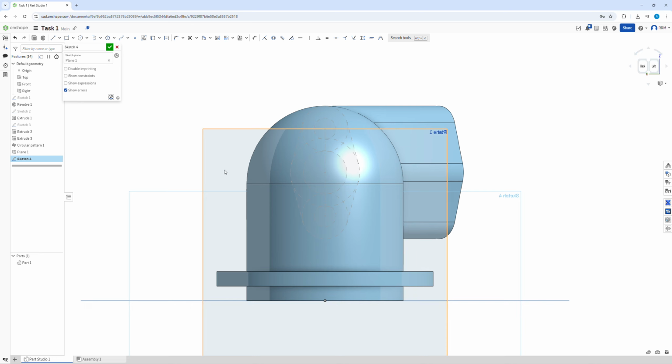Okay, that'll be fine. And now we want to get our line. So our center line from here, constrain it, take it out. Q for construction is what I should have done. So you can click on it, press Q, and that is now a construction line.